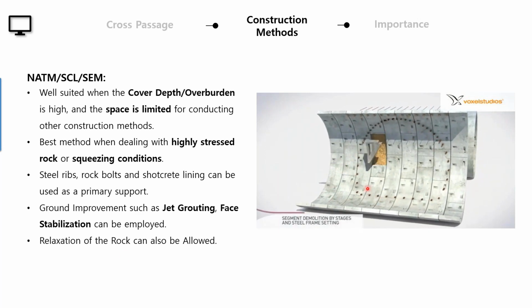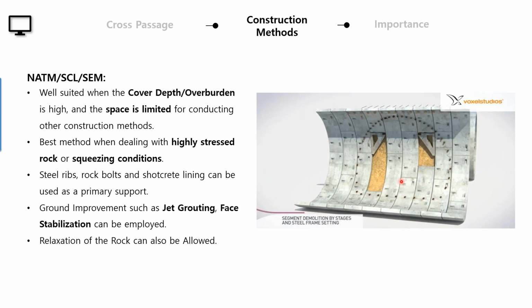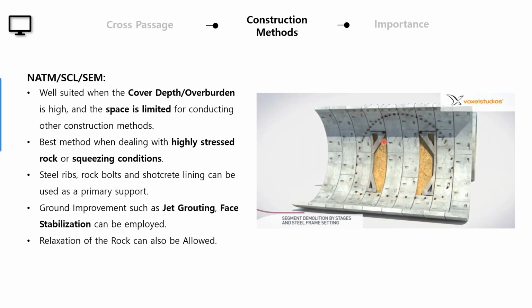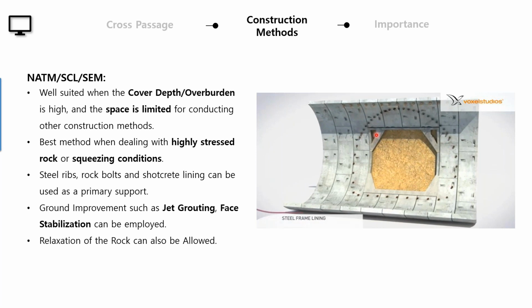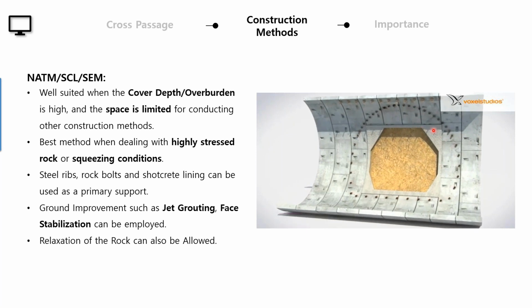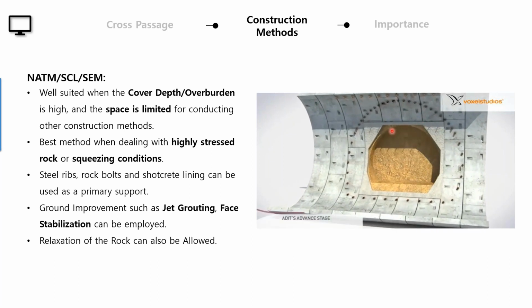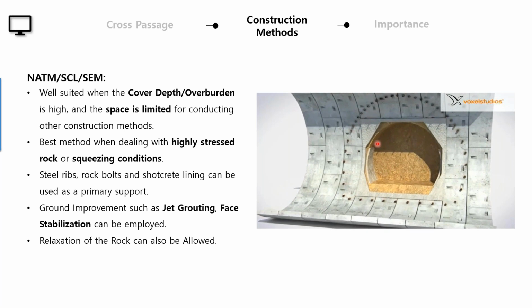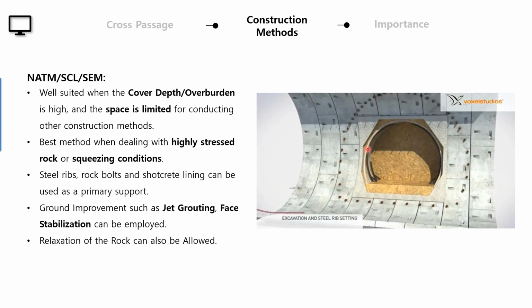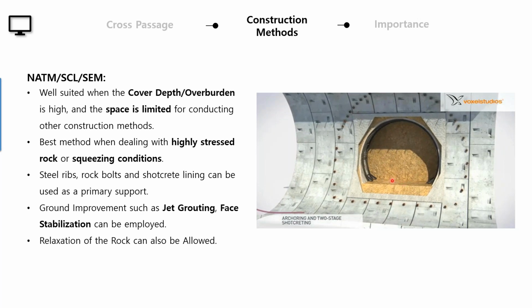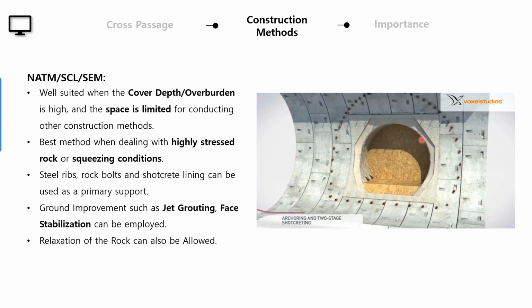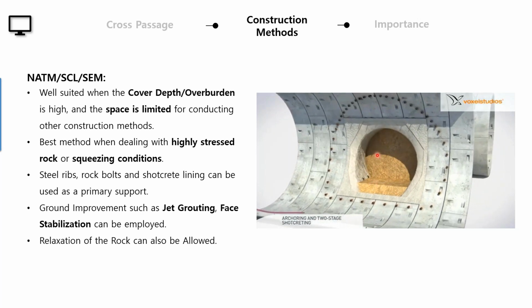So here you go. We are removing the main tunnel lining in the video that you are seeing. And then we are confining that area, providing steel frames and then providing the concrete to fill the gap. And then excavating, the full face excavation happening, followed by steel ribs. And then let's say rock bolts are also placed. And then we have the shotcrete lining.